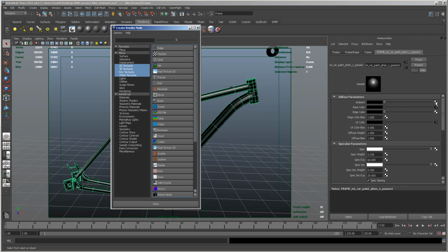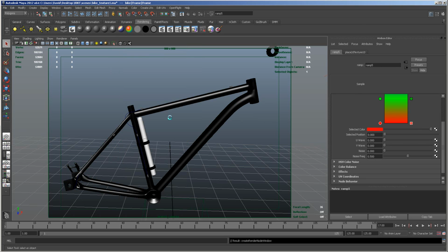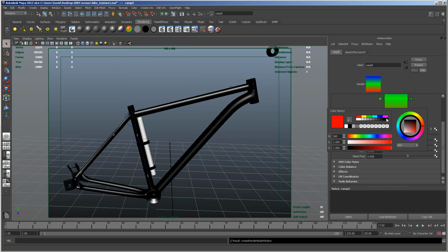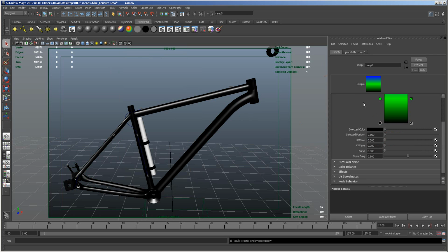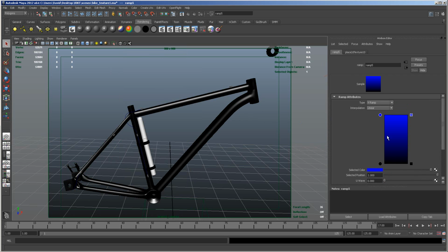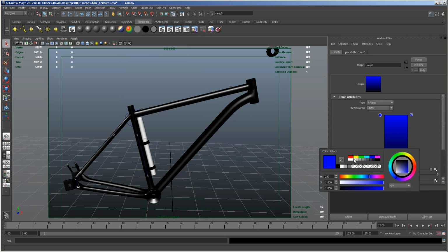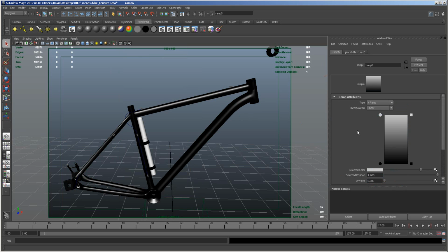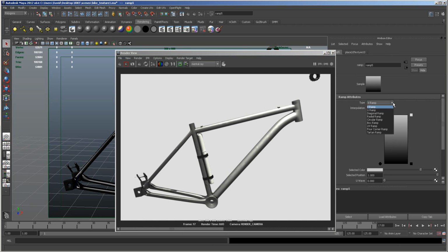Yeah, I'm going to plug the ambient into the ramp, and ambient's going to hit more light, so it's going to appear darker at the back, which is what we want. And the front is going to, so literally there'll be no ambience at the back, and at the front there'll be a lot of ambience, so it'll show up more. So with that plugged in and with it turned to a U type, we'll render this one out.